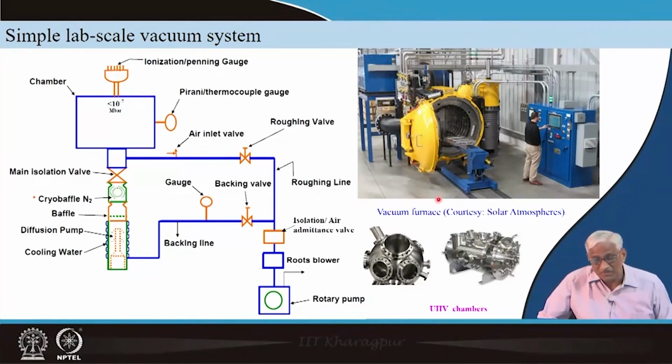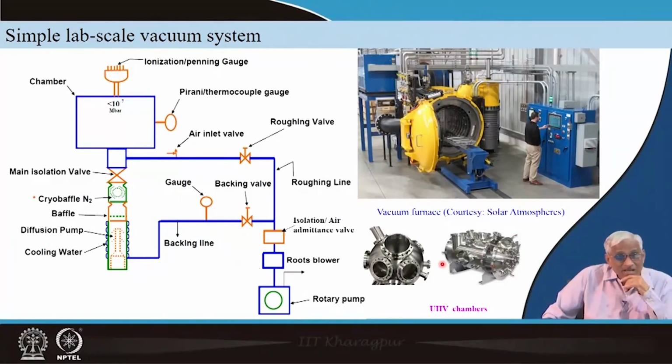If it is a furnace of 10^-6 torr, but if it is an ultra high vacuum system, you have to keep track at various levels: components, joints, everything, and how they look, what type of polishing has to be given inside. Outside also if you polish it will look better, you cannot put some paint, but inside polishing is sub-micron level, and couplings, joints, flexibility and design of interconnecting pipes, choosing the pumps in UHV chambers is a different game. That we will see when we are discussing applications.